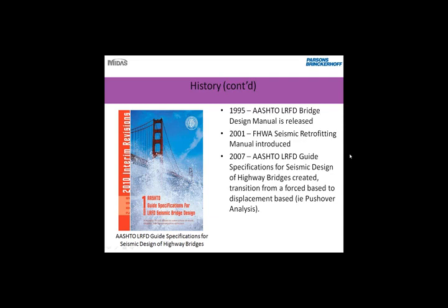2007, the AASHTO LRFD guide spec for seismic design of highway bridges is created. And this highlights the transition from a force-based design, which we're used to in the AASHTO LRFD, to a displacement-based design. This is kind of understanding that in the event of an earthquake on a major structure, the structure is not going to behave elastically. Depending on the structure, it won't behave elastically, and we should probably be looking at more of the expected displacements that take place in a seismic event.